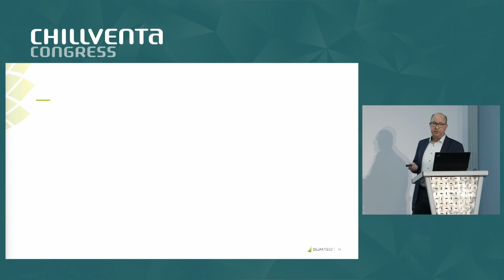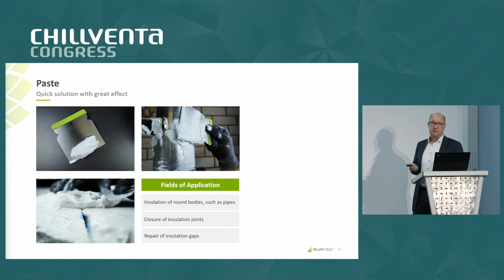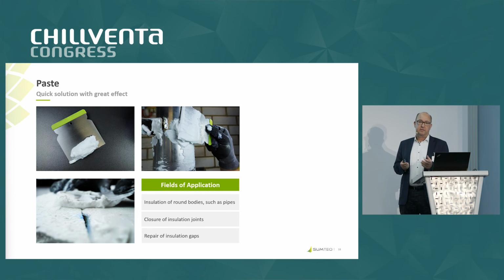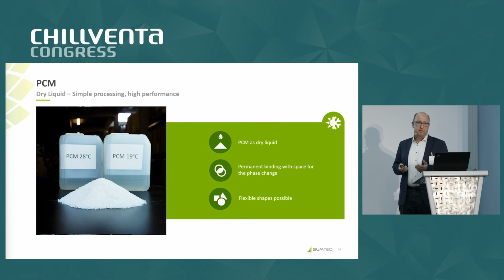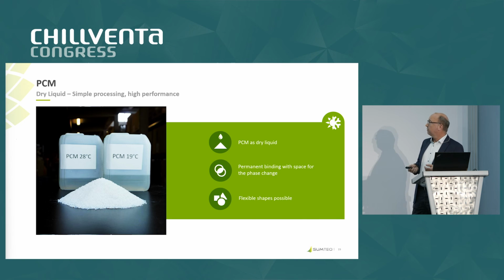A completely different use of Samform is microencapsulation. If you don't use the structure of the nanopores for insulation, you can absorb oleophilic substances with the foam, for example phase change materials. And so you have no insulation anymore from the pores, but the phase change materials you can choose.